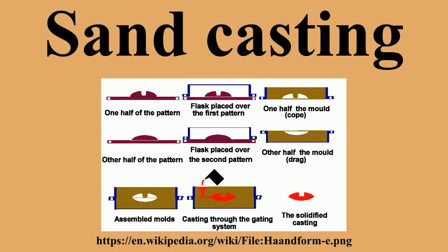Cold box uses organic and inorganic binders that strengthen the mold by chemically adhering to the sand. This type of mold gets its name from not being baked in an oven like other sand mold types. This type of mold is more accurate dimensionally than green sand molds but is more expensive. Thus it is used only in applications that necessitate it.